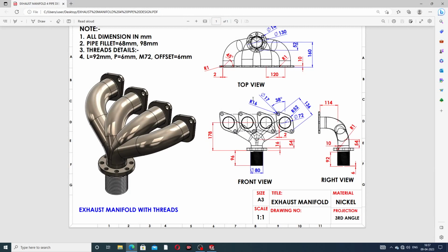Next, draw this circle here, and this circle is also used for a pattern. This circle is big, diameter is 130 millimeter, and the center to center distance is 160 millimeter. One point is very important. This point is 178 millimeter, and the direction is downward.